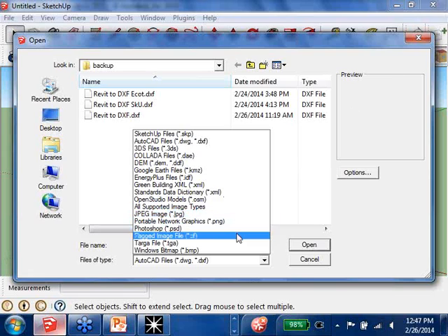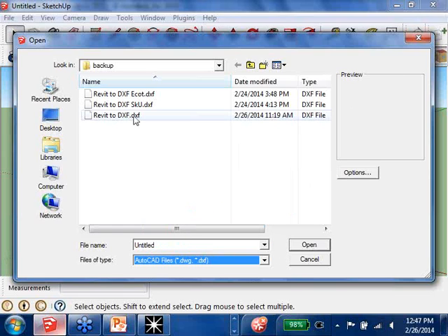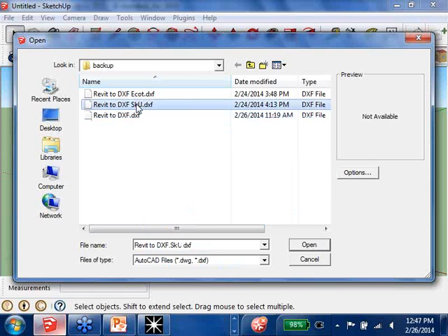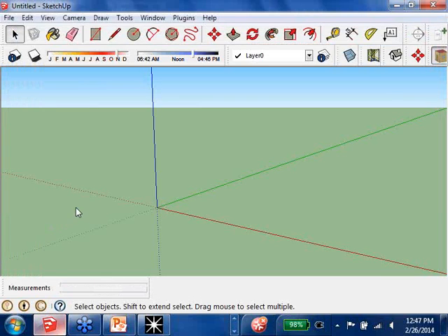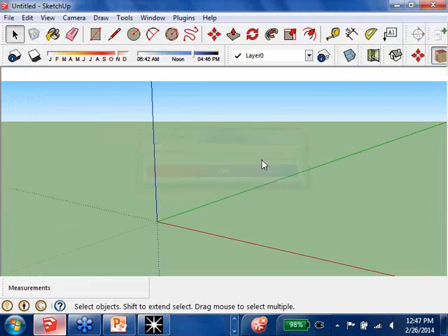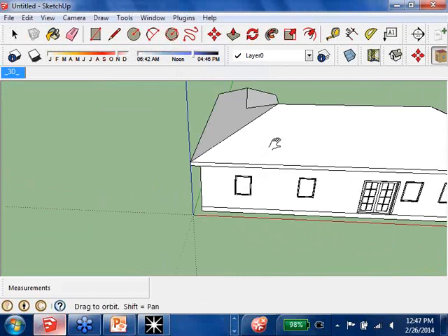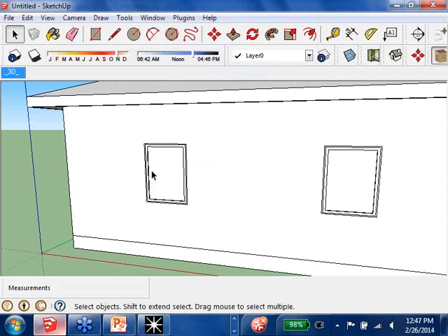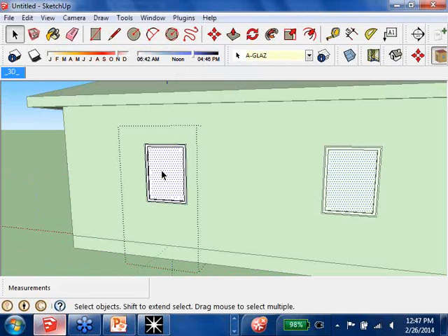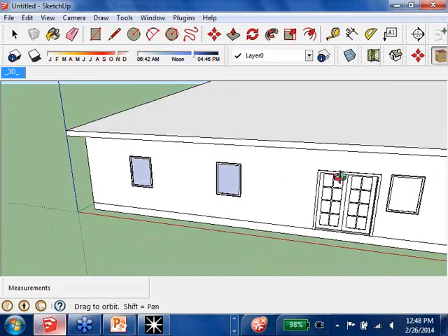And so I'll do the DXF really quickly. And in SketchUp, I actually prefer when doing the DXF or DWG. The main reason being is it also creates components. So you see when I select this window, I told you there was a problem with creating 2 window panes. You're able to delete all of the second window panes in one simple step instead of having to go to each individual window and deleting a pane.